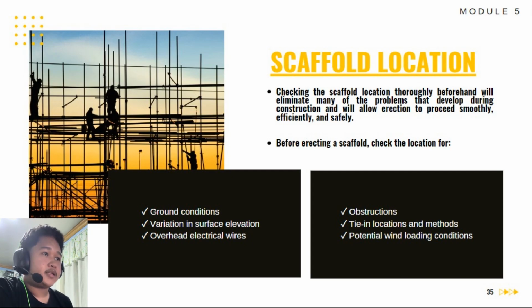Before erecting a scaffold, check the location for ground condition, variation in surface elevation, overhead electrical wires, obstruction, tie-in location and methods, potential wind load condition.